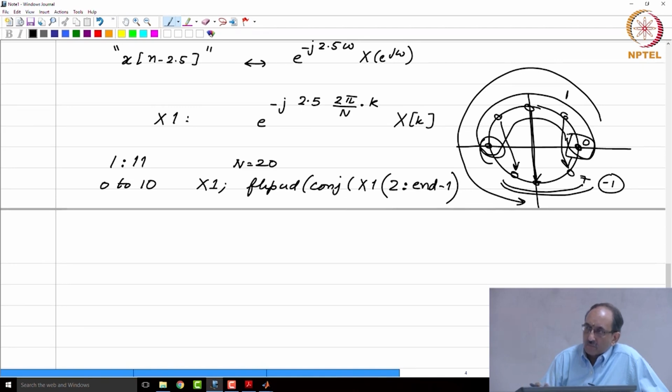So, after having now learnt DFT, now you can appreciate the MATLAB code that was part of this example. The main things are, you replace omega by its sampled value, and then you only need to compute this for the first part, namely in the range 0 to pi. From pi to 2 pi you can repeat the information that you formed in the range 0 to pi.